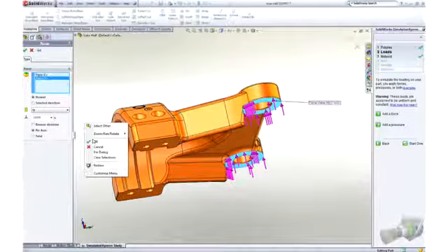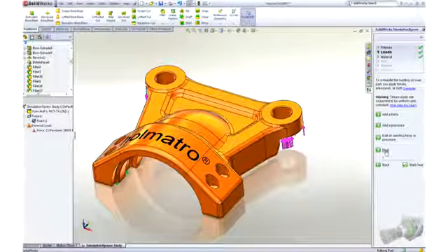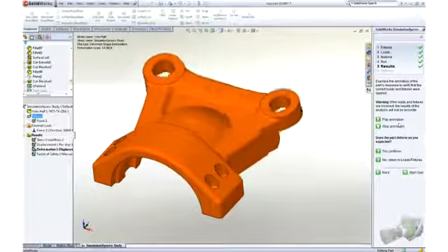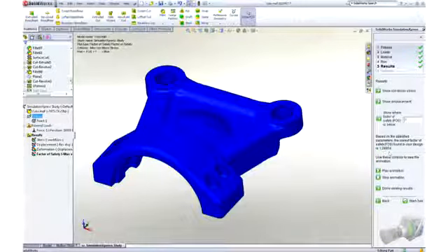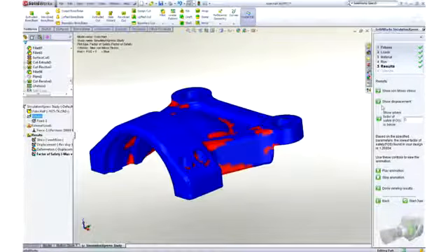The checklist on the right-hand side makes sure that you have everything ready to test out your design's performance. After the simulation has run, you get immediate visual feedback on how the part is trying to deflect, which is great to confirm the test is set up correctly. It's easy to verify the factor of safety, stress, and deflection of the component.